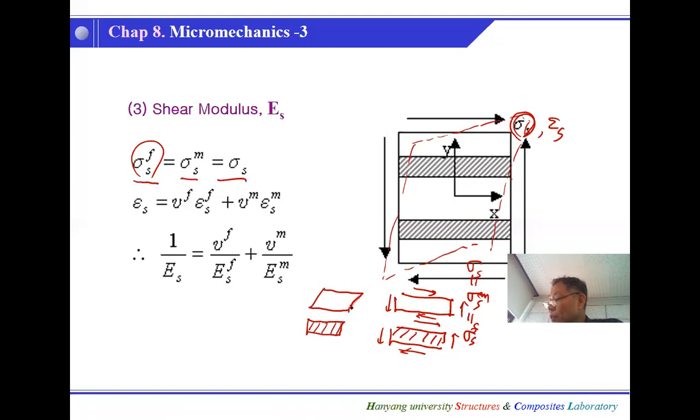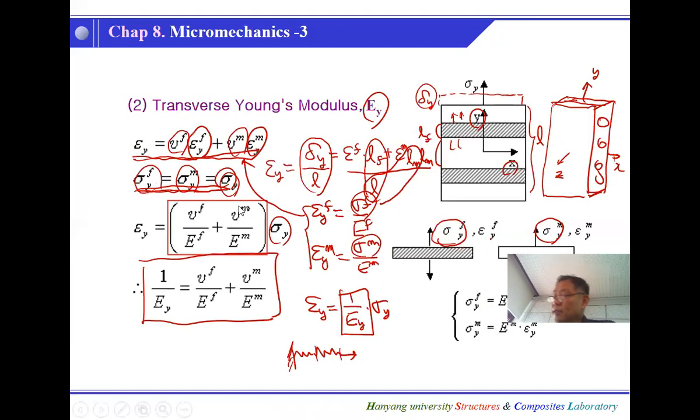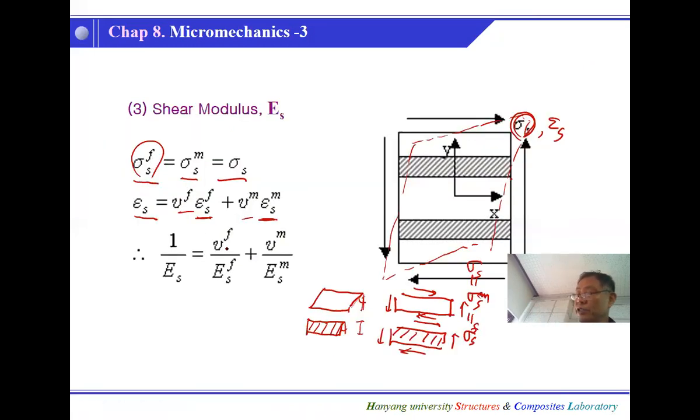So average-wise, we consider pretty much the same as the previous one. This is the length and this is the length. So we calculate this angle and linearize them. And so the ply shear strain will follow this rule of mixtures with fiber and resin volume fractions. And exactly the same as here. Exactly the same, and skipping the detailed procedures, the shear stiffness of a ply will follow this inverse